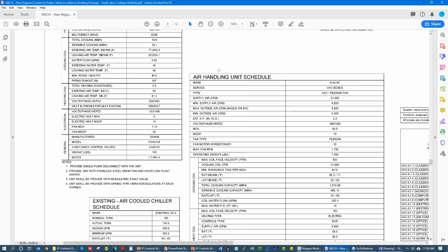So my recommendation is that on large pieces of equipment, utilize a star pattern directly to a switch. I get what they're doing by including additional ports, but I would recommend utilizing those additional ports for ancillary equipment associated with the space. Like maybe you've got a light that you're using IP with, or a local screen, or a camera, as they mentioned.